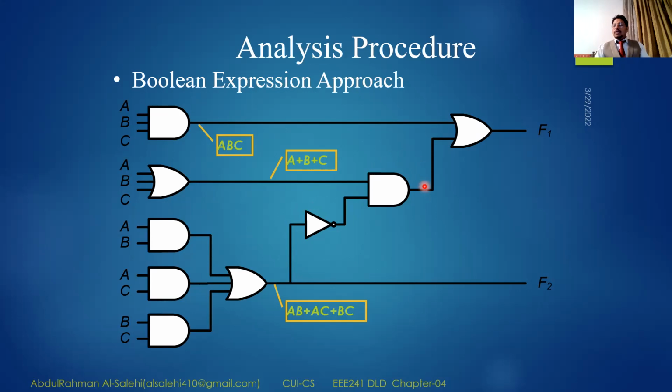Again, when we invert it, you remember what we did in the last lecture when we were discussing Verilog, how when we write our module programming for that, we give every gate a small time, a nanoseconds, for example. In the first example we did, we gave the ANDing gate 30 nanoseconds, then we gave ORing gates 20 nanoseconds, then we gave inversion like 10 nanoseconds.